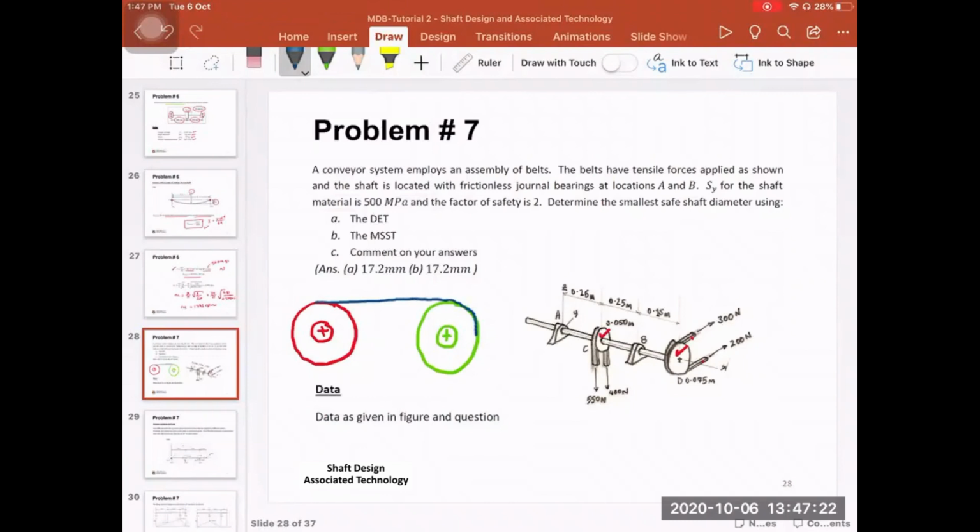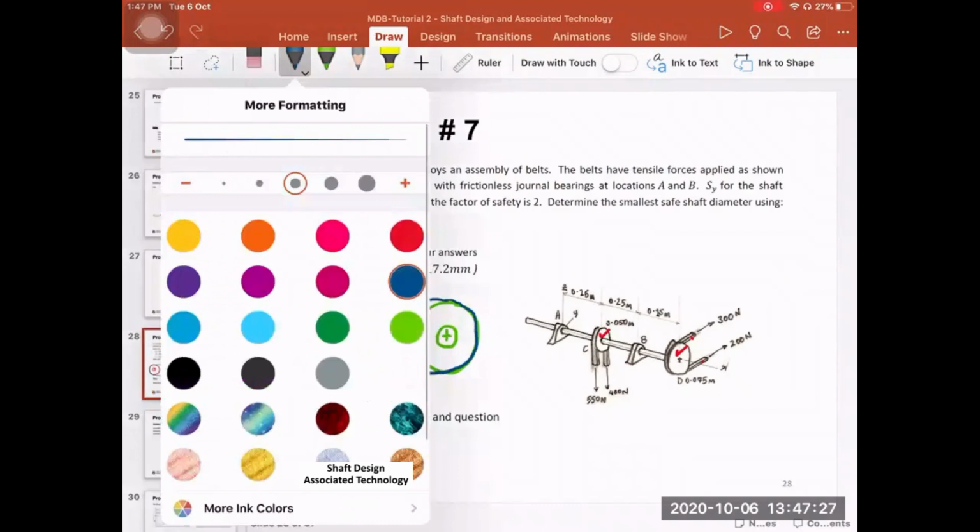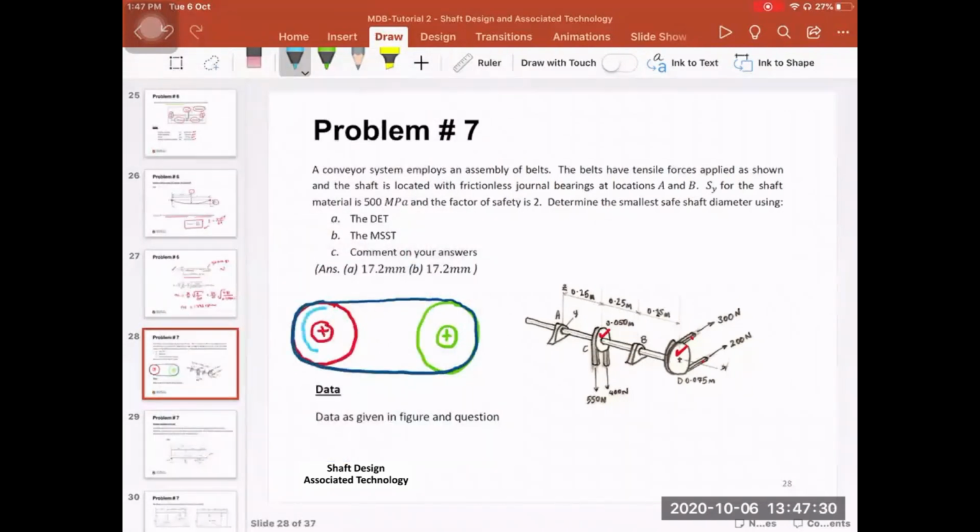the belt goes around the pulleys like this. And if this shaft rotates in this direction, this shaft is going to rotate in the same direction. Of course, you can use a smaller pulley here and a larger pulley here, just to increase or decrease the speed. The idea here is that when we use this kind of configuration with the chain, we said that we have a tight side and a slack or loose side, and the force on the loose side is equal to 0.